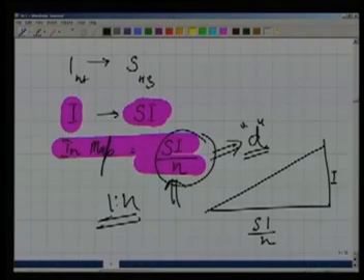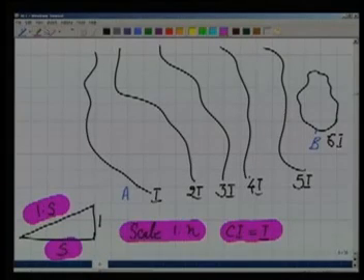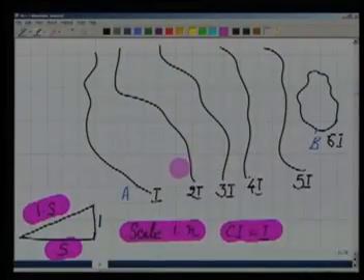Now in my map, starting from a contour over here, I should move a distance equal to d in order to reach the second contour. If I move horizontally by d and I reach the second contour, then I am maintaining a slope of 1:s. Now how to do that?